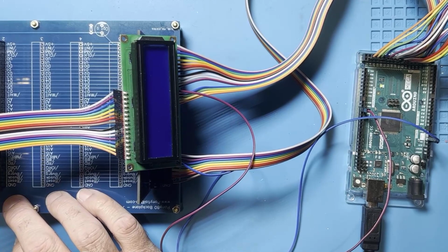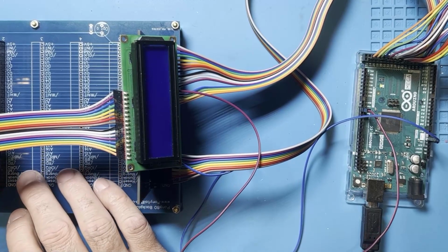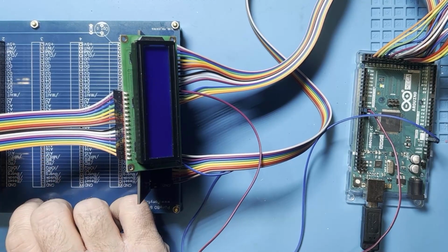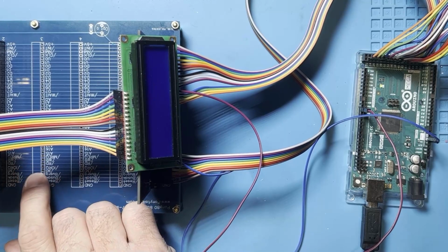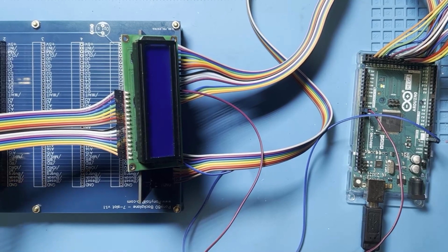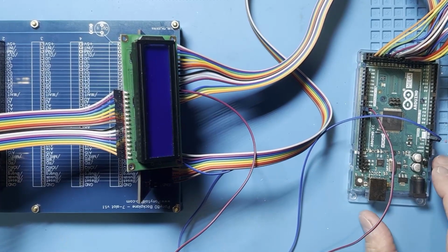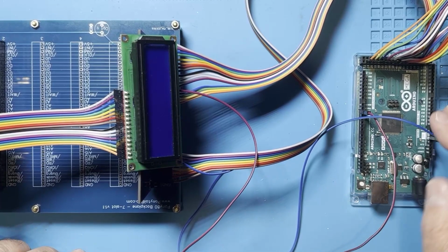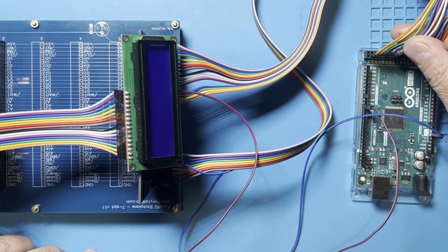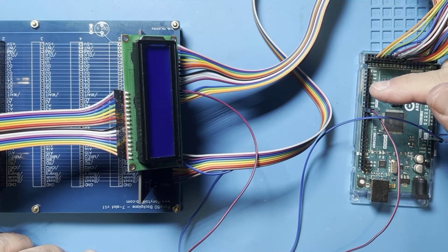I wonder if there's something causing a data or address pin to float rather than go either high or low. So let's do an experiment here. What I'm going to do is disconnect the Arduino. I don't think we need that since it works with it. I'm going to take these lines and hook them up to some 10K resistor arrays so we can pull them low, and then try this again and see what happens.